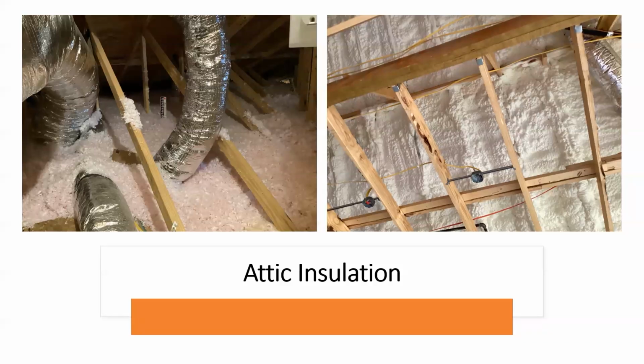Brad asked, does mid-floor insulation count to hold in rim joists, or does it need to be mechanically held or encapsulated? That's a good question, Brad. Does it meet the intent of being permanently held in place? That means making sure that insulation stays in contact with the rim board.